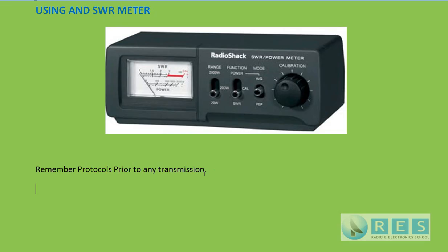The next thing you need to do: you've probably made the announcement on single sideband, you now need to change to a mode that has a full carrier. Single sideband is suppressed carrier. You need a mode that's going to transmit power when you're not speaking into the microphone. So you could use amplitude modulation, that's double sideband, or you could use CW, that's Morse code, or you could use FM. Any mode that will give you a continuous carrier. You don't want to be talking, you just want to transmit a continuous carrier.